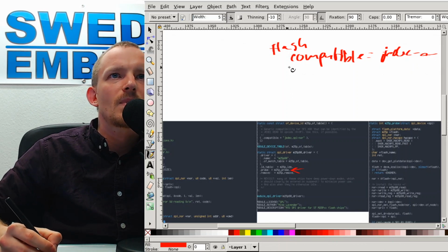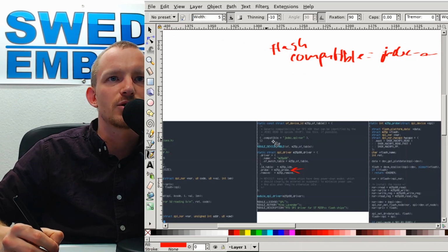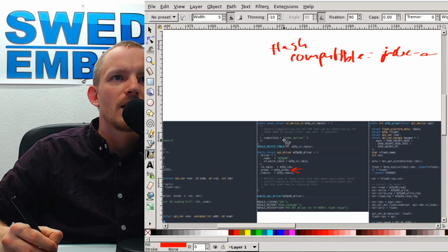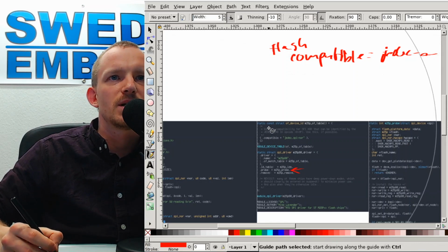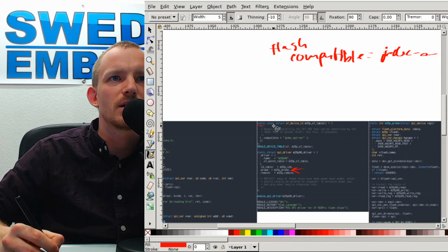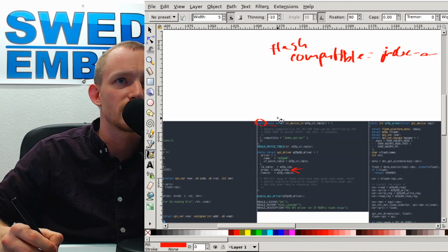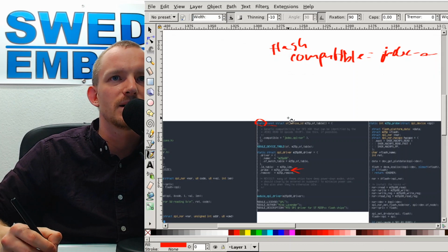And when the system is parsing this section, it's actually going to check the compatible string, and there are a whole bunch of different compatible strings with which this particular driver is compatible, but this one is the generic one. So this one is set by default. So we define this table as static const, which means that static means it's visible only in the current file. Const means that it's not going to change, which means also that it's not going to be placed into the data section where the data can be changed. It will be just a constant placed directly in the firmware.